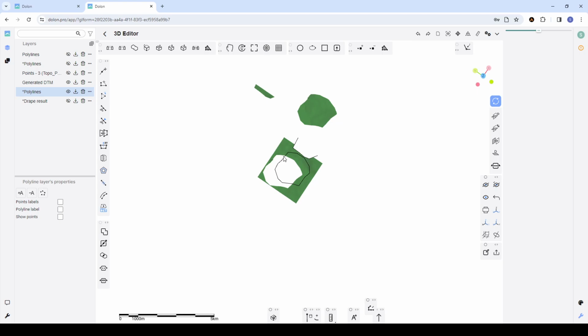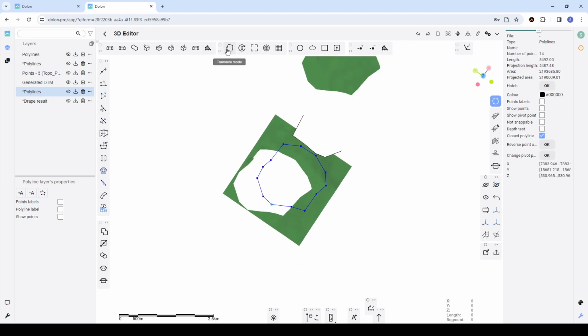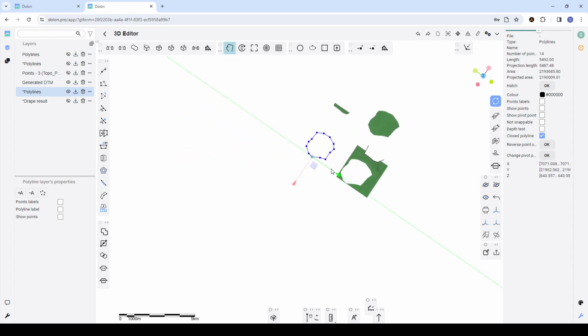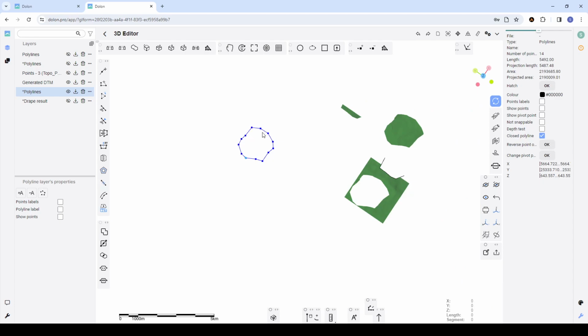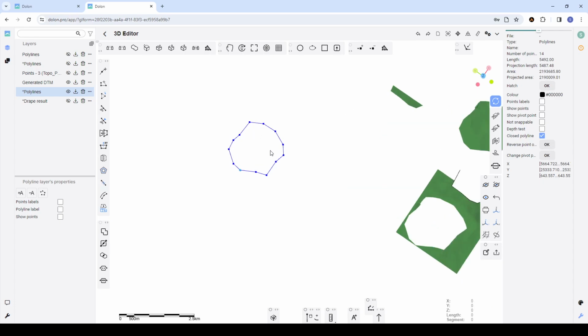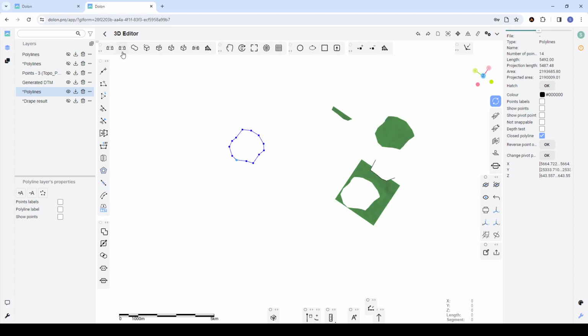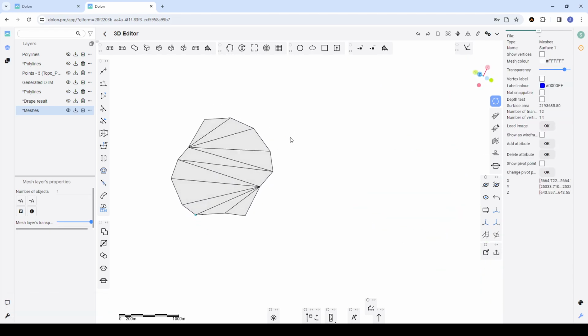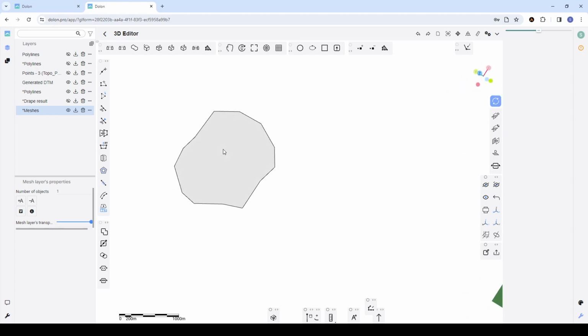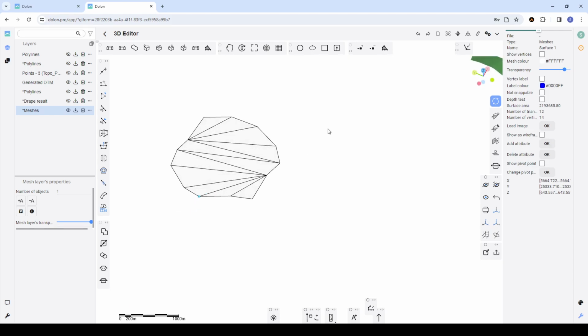Now let's triangulate some polygons. So this polygon, right? Let's move it to this place. And we can just triangulate it. Triangulate it means from this polygon we can create wireframe mesh. So for this purpose, the polygon triangulation, this button. There are several options how to triangulate it. So minimum area for 3D polygons, we will use this option. And yeah, here it's created, but you can see, because of the perspective, it's somehow transparent.